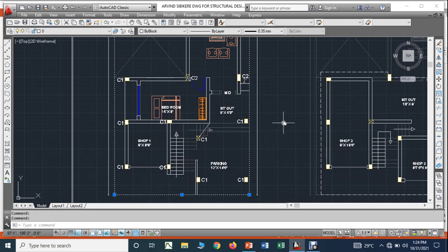So keep it in mind, students, whenever the plan is going to be designed, the first and foremost step of an engineer is to go to the corresponding site. Either the site engineer, if present, or the structural engineer himself may have to go to the site. So then what are you supposed to do at the site? You are supposed to note down the boundary of the given plot.